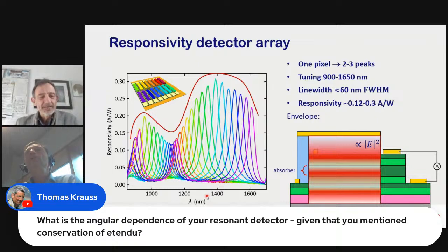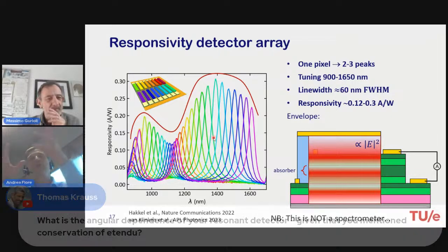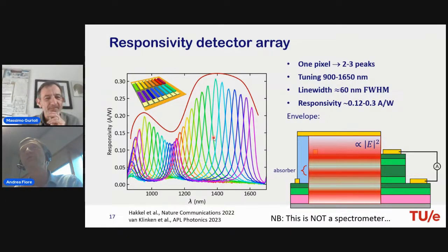And this is actually the main reason why we chose a very simple Fabry-Pérot structure, because among the things that you can do easily, it is the one that has a relatively low angular dependence. It just goes as a cosine. So that is, for that reason, a good choice. In absolute terms, I think for an NA up to 0.2 or so, for this line width, there is a negligible wavelength shift with the angle. Of course, if you go beyond, you will see it. It's not necessarily a problem as long as you have the same optical system. If the object is always, for example, in contact with your module box or whatever, the angular distribution is also more or less constant. That is fine.